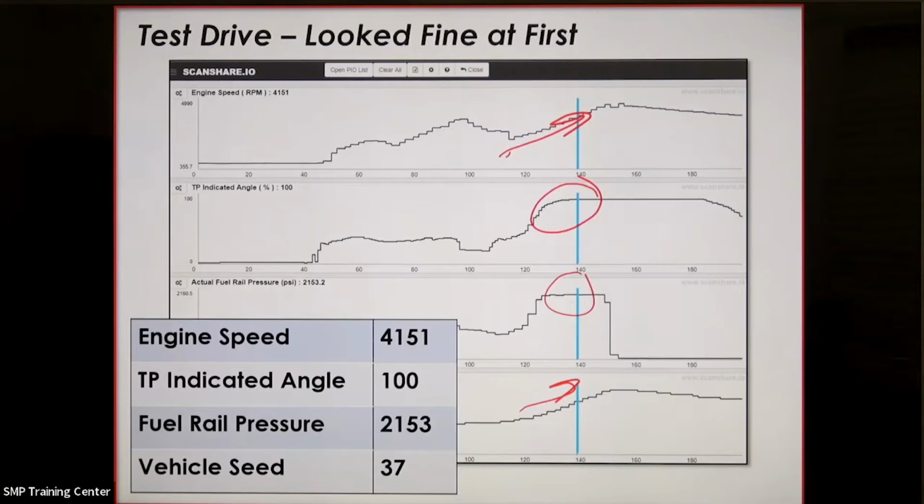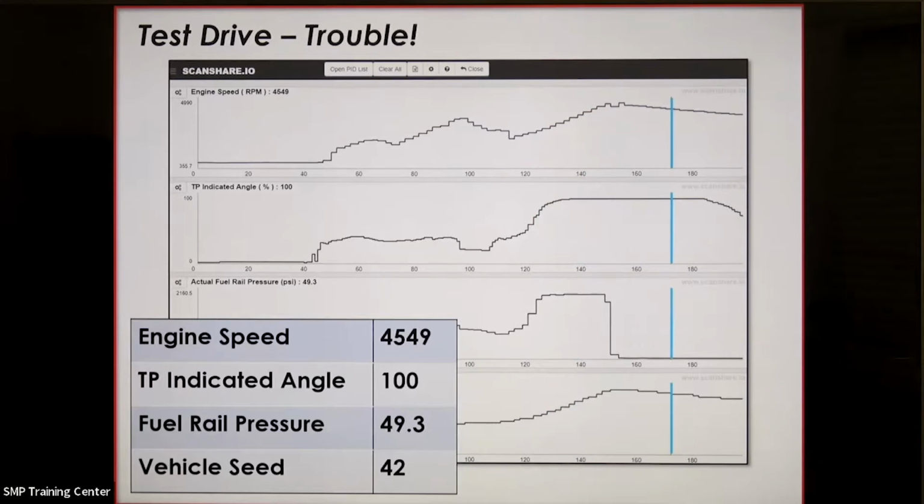We're increasing in speed. But what happens a moment later? Well, right here, you see something happened. Our fuel pressure just completely fell off. And you can see the engine RPMs are now going down, down, down. Now, that's not because he let his foot off the gas. He has his foot buried into the carpet still. But the engine RPMs and the vehicle speed are going down, down, down. Because why? Because our fuel pressure dropped to just below 50 PSI.